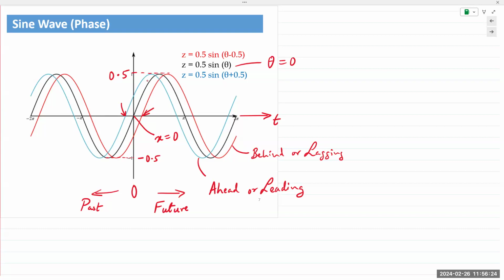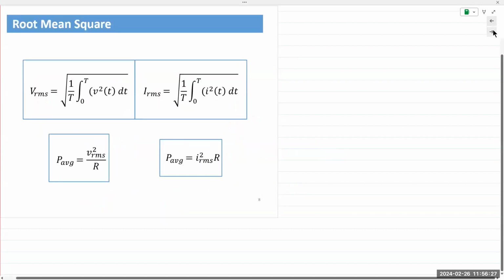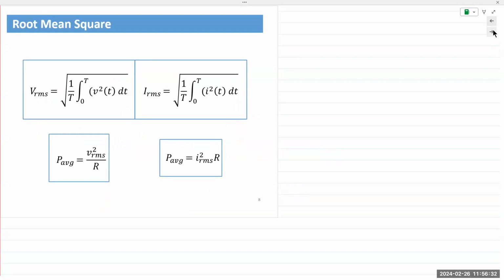Okay. What is the average value of the waveform? An AC waveform, positive and negative. Half of it is above, half of it is below. What is the average value? 0. Yet power and energy is being supplied and delivered, right? So when they first came out with means of generating AC currents and AC voltages, when it's supplied, the light bulb turns on, energy is being delivered to the load. But they needed a mathematical way to actually describe that quantity. They take the average, it's 0.